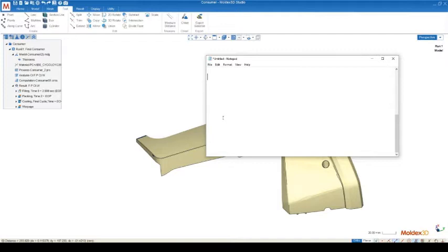Most of the time when I'm looking at optimizing any sort of process for anybody, I will first look at the cooling, because the cooling takes up the largest chunk of the cycle time pie, if you will. If everything were converted to percentages, the cooling time would take up the largest chunk of that pie. But that's not to say we can't optimize all of the other three, or I should say the other two components. So the filling, packing, and cooling can all be optimized.